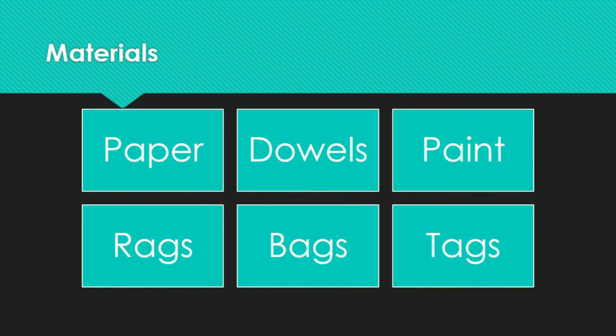You also need rags, which are usually for general cleaning and removing preservatives from equipment and other items, as well as disposable plastic bags to store all hazardous things during your inspection process or your pole maintenance or treatment process. And lastly, you also need identification tags, which are affixed to poles and list the date of inspection, the contractor's name, as well as the preservatives that are being used.